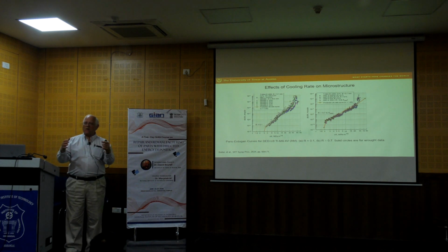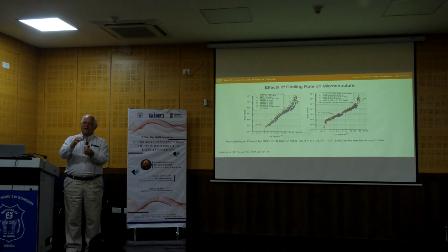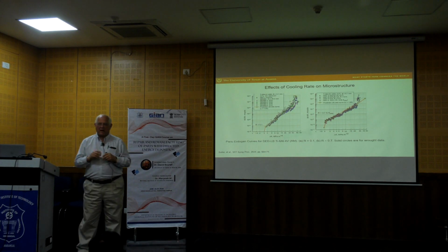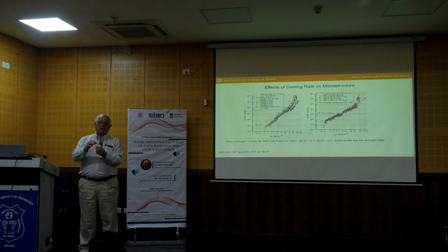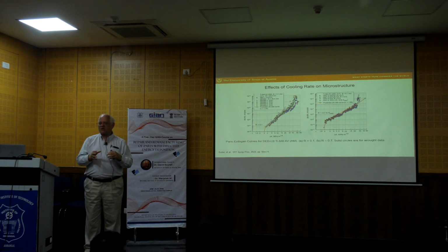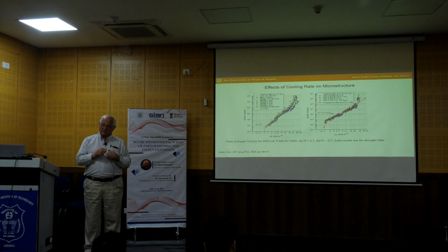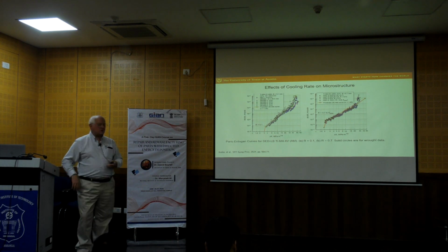And so as the crack grows, I could be doing a constant stress amplitude test, so the change in stress doesn't change. I'm loading from 0 to 20 megapascal, for example, and it will be that way all the way through the test. However, as the crack grows, the stress intensity factor will increase. And again, the stress intensity factor is basically the stress times the square root of the crack size. So the stress stays the same in the cycle, but the crack size gets bigger, and so my stress intensity factor gets bigger.